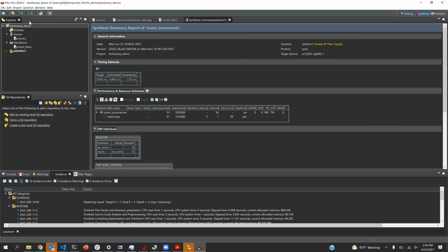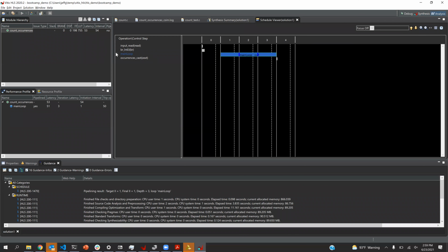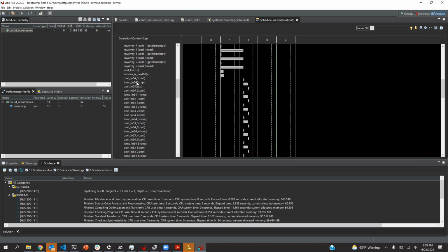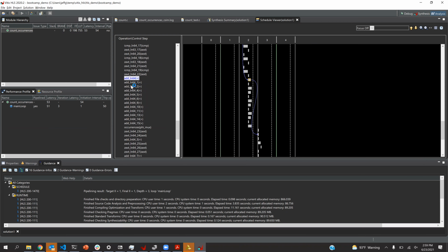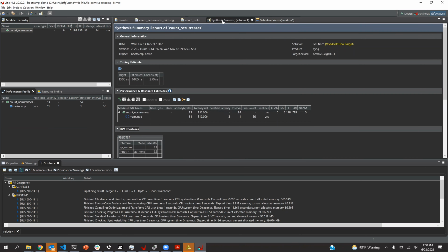So essentially now every clock cycle we are getting 20 things out of memory. And I think we need a lot more adders now, right? We have to do all of those additions. Let's go look at this thing. Okay, if I expand this, now I've got all these additions going on, and you should see now we're at 755 LUTs.